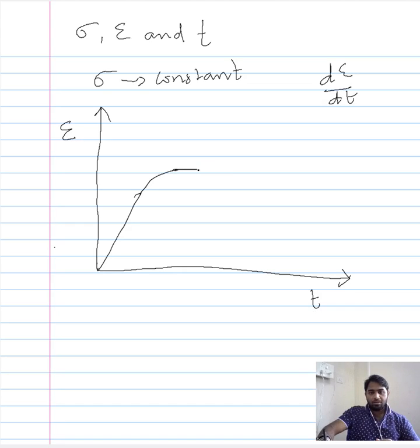we have a region wherein there is just a marginal change in the strain or creep. Over a period of time there is only a marginal change in the creep, and this we categorized into the second stage, and we also refer to it as the steady state creep region. Immediately following the steady state creep region, there is a significant increase in the rate of strain, and that means there is an accelerating creep which ultimately leads to the failure of the material. So this is what we previously saw, how we can categorize a typical creep curve.